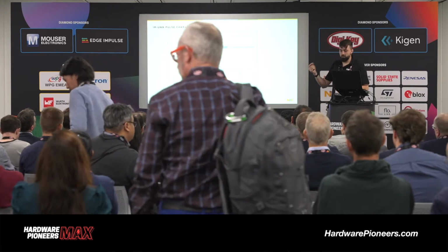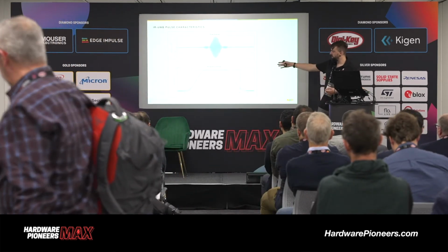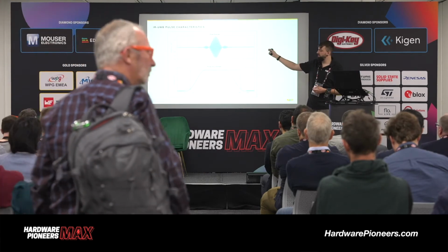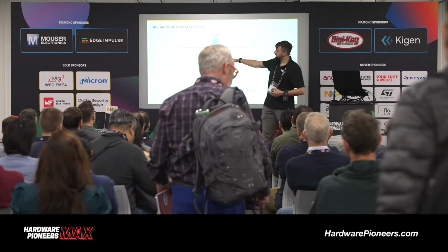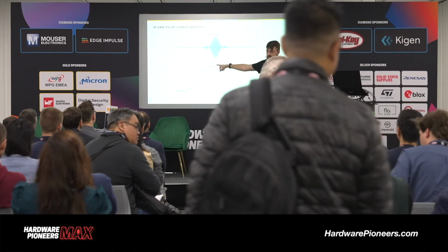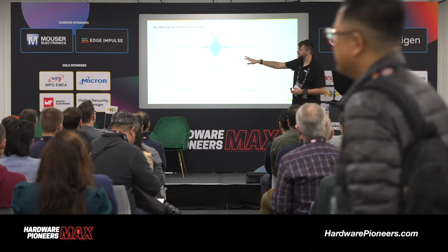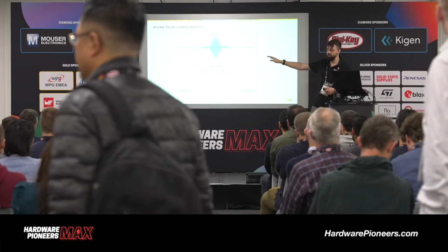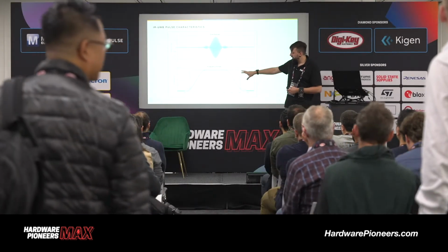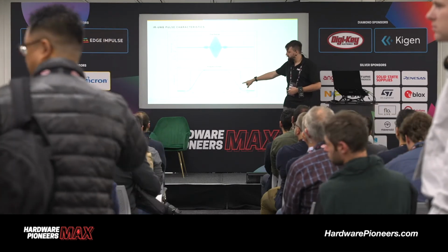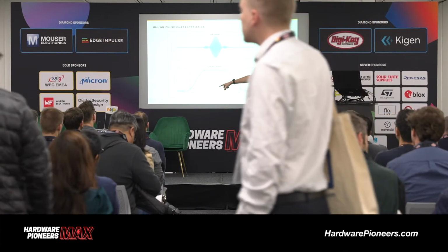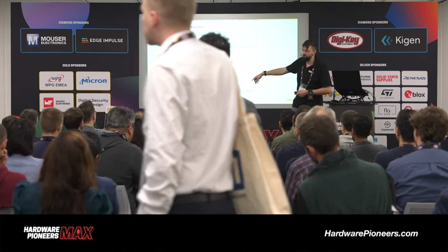So I talked about the short signal duration. I'm showing you here one definite signal pulse. As you can see, the signal duration is here in nanoseconds. It's only 4 nanoseconds wide, which is very short in comparison to other signals like Wi-Fi. And here we have the frequency domain of the signal, which of course shows you that its bandwidth is more than 500 megahertz.